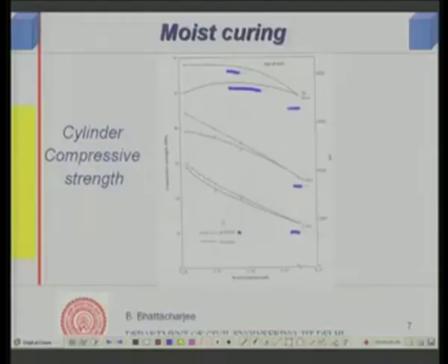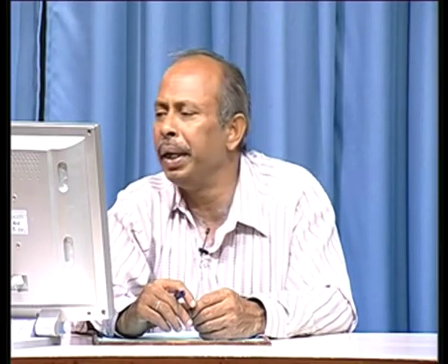At high water cement ratio, these effects are less pronounced, because after all very high water cement ratio, this is somewhere around 0.42 or 0.43 maybe, somewhere around that kind of situations. Well, ponded and Hessian tend to give you the same, because there the capillaries would be relatively more, and generally the effects of curing by ponded and Hessian remain the same.